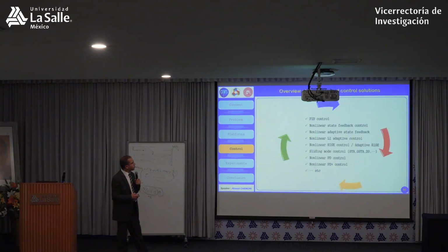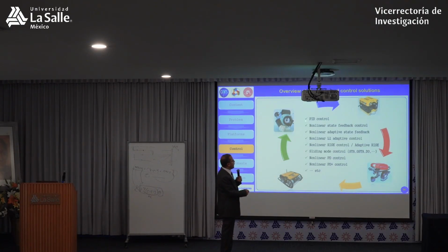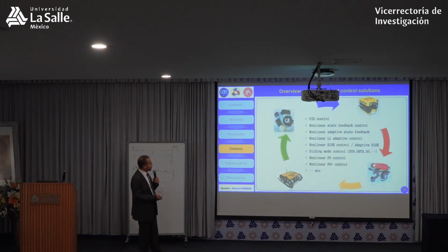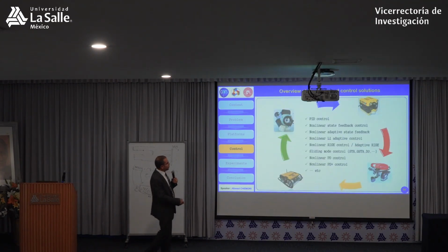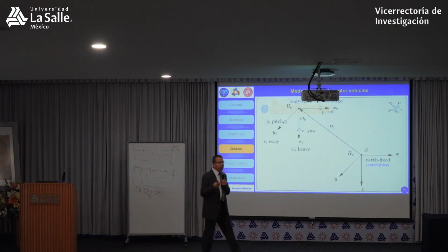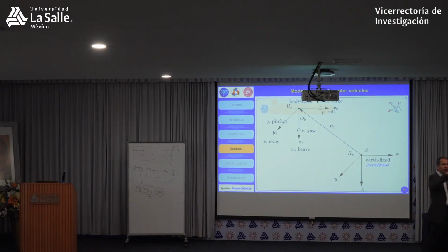of Control. Now, for the vehicles using classical propellers, we designed controllers, starting with PIDs, the step 0, the level controller, and then we started developing a lot of controllers: nonlinear, adaptive, RISE, sliding mode, and so on. And now, for most of the controllers, especially if you want to start with simulation, you need a dynamic model. For the dynamic model, it's not like robotic manipulators, where you apply Lagrange and you find your dynamic model that can be used for simulation.